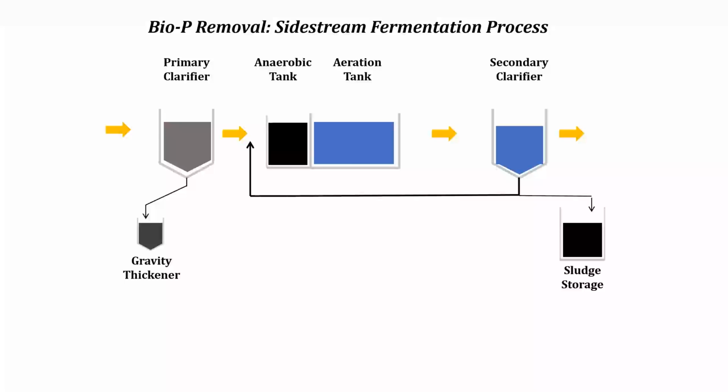This is like your basic AO design, anaerobic tank, aeration tank for phosphorus removal. Primary fermentation. The primary sludge is also often fermented. So it's just septic-like conditions, not quite anaerobic enough to create methane gas, right? Because that destroys our acids and our acid alkalinity ratio. So we want almost septic, or we want septic conditions.